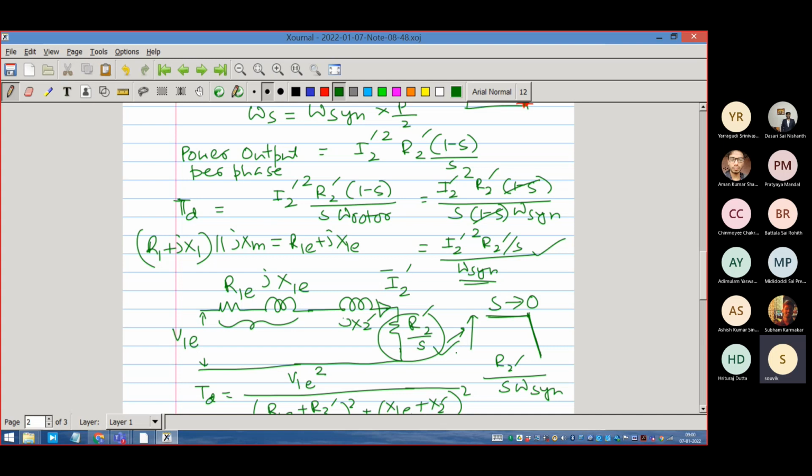So we will be making this approximation because we are operating in that specific zone. We don't operate in the long zone of positive torque speed. We are operating only in this zone, because we'll see that the copper loss in the machine is proportional to the slip.